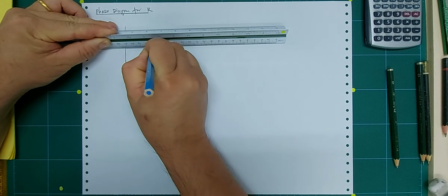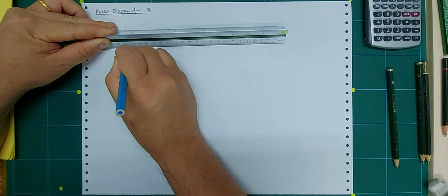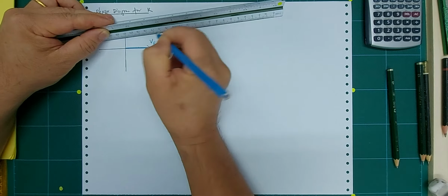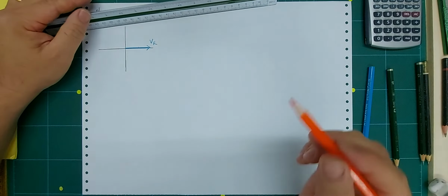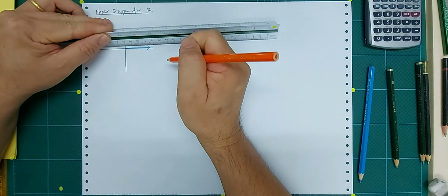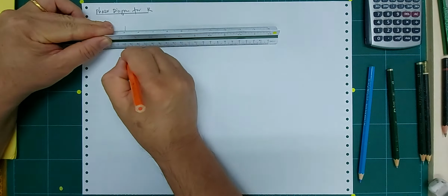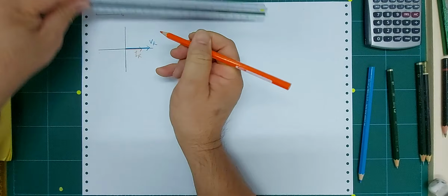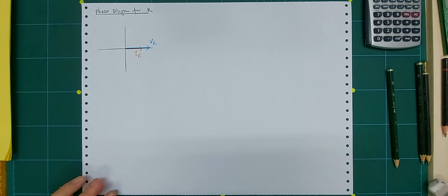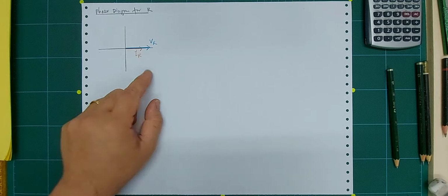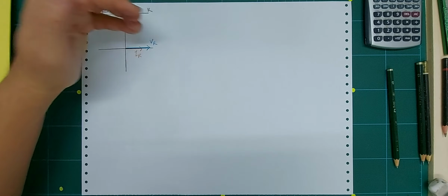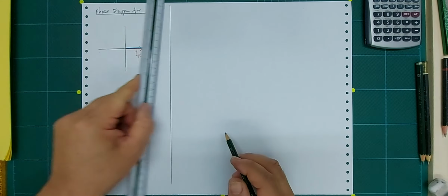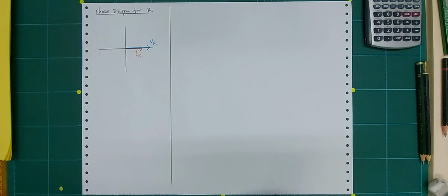So when the voltage is here, I call this one VR. And the orange color is for the current. So the current and voltage are in phase. That means they point in the same direction. So that is our IR. That is how you represent the relationship between voltage and current using a diagram like this. This is called a phasor diagram, PHASOR, something like a rotating vector.